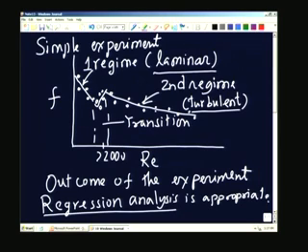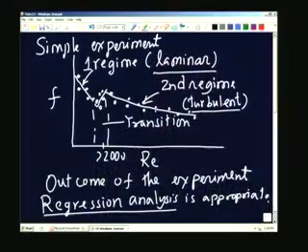you can take with large number of levels, and in fact many times what we do is to cover the entire range, we may even change the fluid from one which has a lower viscosity to higher viscosity and so on and so forth. So, the Reynolds number being a single factor, it can be obtained by various combinations, and we look for these combinations which give a particular range of values, and therefore we will be able to cover the entire range. So, with this we have more or less come to the end of experimental design,